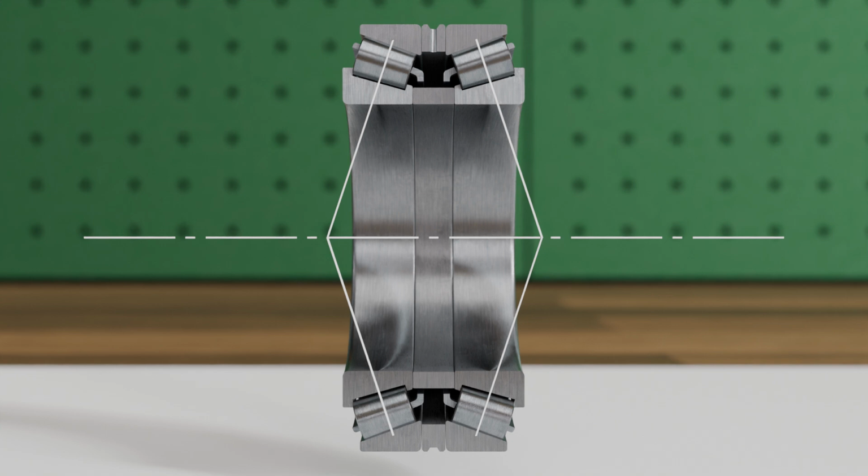making it preferred for applications with high demands on bearing guidance. Since the bearings are delivered from the factory with defined clearance or preload, complex adjustment during installation is not required. Matched tapered roller bearings are especially used in axle bearings, gearboxes, and machine tools, where axial forces must be reliably absorbed in both directions. Tapered roller bearings can handle very high radial and axial forces, but tolerate almost no misalignment or shaft deflection. This is especially true for cylindrical roller bearings.